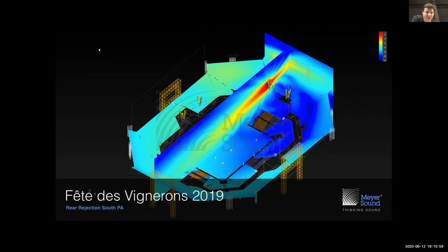So it was careful angling in this, and the rejection under the speakers was critical for the microphones, as Martin mentioned. So that was defining the length of the array, and I was questioning it sometime before if we could skip some Leos, have less speakers, and eventually we had to settle with 16. The reason was we wanted a beam narrow enough that would go across the stage without interfering with the choirs that will be placed in front, as you saw in the previous picture.